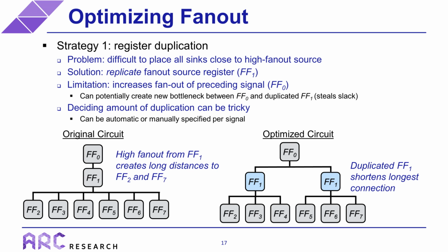One quick note about doing register duplication manually. Synthesis tools will by default synthesize away registers with the same functionality, which is what we have here with the duplicated registers. So the synthesis tool would basically get rid of all the duplications. So before you spend a bunch of time explicitly coding duplicated registers, make sure you look at how to disable this optimization in your synthesis tool. Or you can look at the fan-out code example on the repository where I will demonstrate how to do this for Quartus.